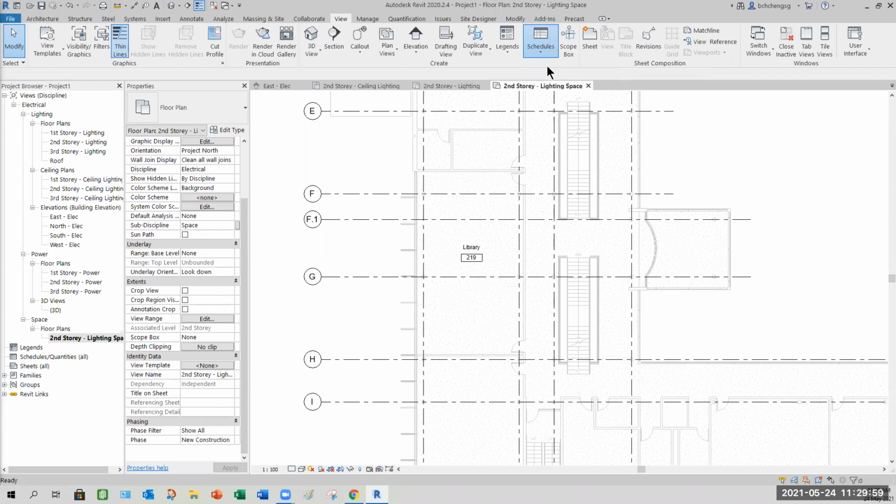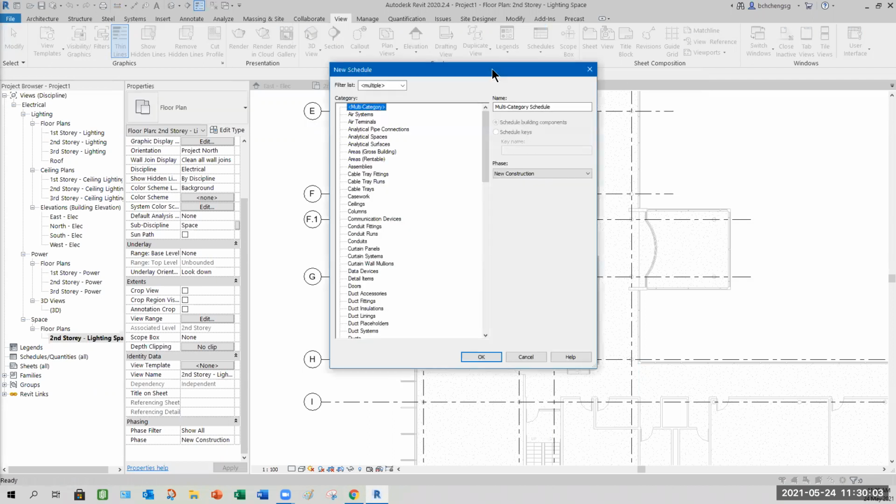Okay, so get the tools out. It looks like this. You want to create a schedule based on space, so we scroll down. Space is the one. Remember just now when we created the required lighting level, it's based on space to perform the calculation. So we must use the same one. The name here, we call it Space Lighting Requirement.